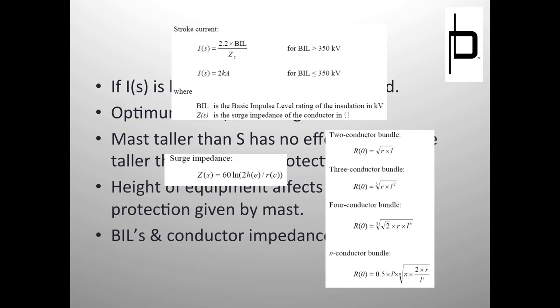as you calculate your protection zones. You definitely want to do a different sphere calculation every time you have a different BIL in your substation. And maybe every time you have a different conductor height, if there's a significant difference. But when it comes to the radius of the conductor itself, that has a negligible difference. But again, to follow the guide properly, you would do that.